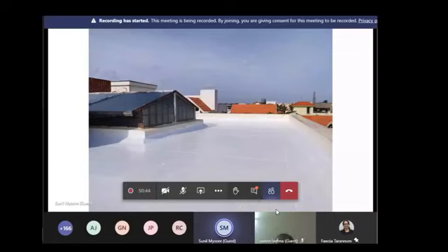So for a white coated roof, we actually take it as 0.92. This is one of the roofs where there is a white coating done, which increases the runoff. At the same time, it keeps the roof clean. White coating also helps you in keeping the roof clean, because the dirt doesn't stick on the roof.